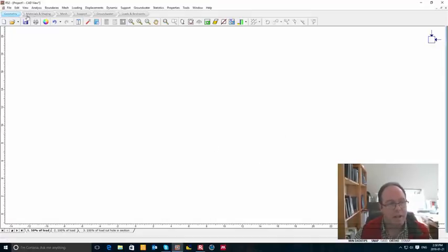Now you can see these little tabs here. They really lay out the order in which most projects are put together. I'm going to start off building the geometry of the model. So it's going to be pretty much a rectangular section with a little tab on the top to put a load on. And so I've drawn it all out, and it's sitting in front of me, and I'll put together the geometry here. So first I'm going to click on Add External Boundary, in this boundaries area.